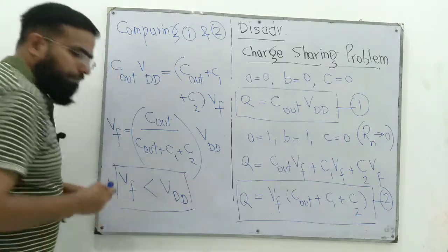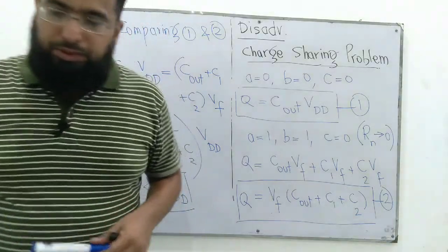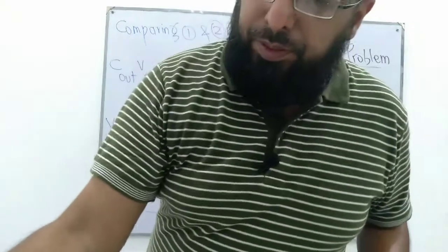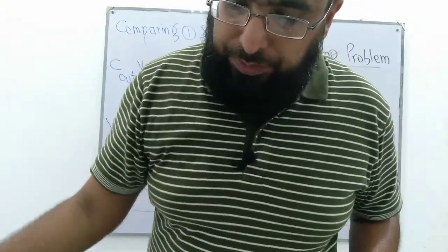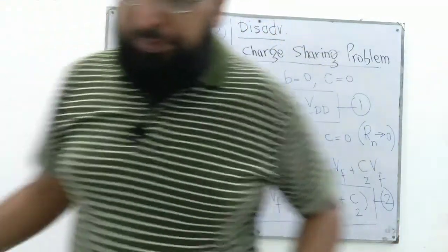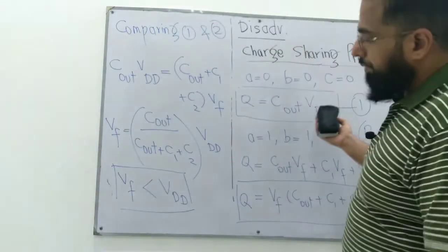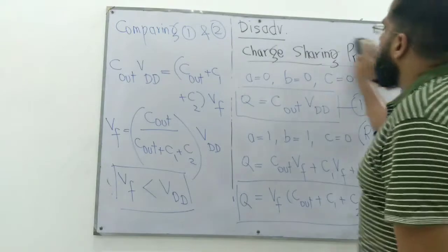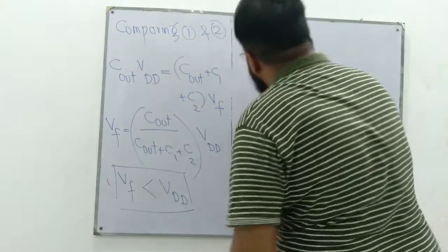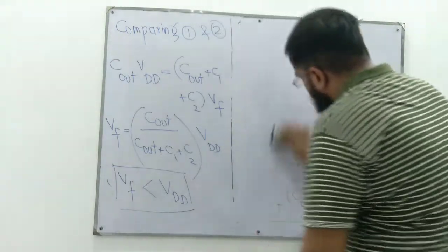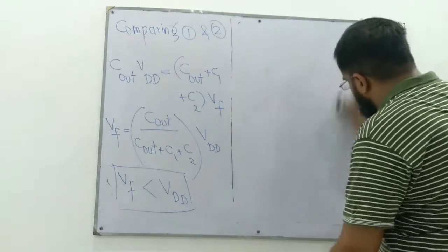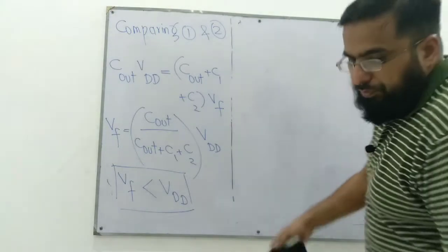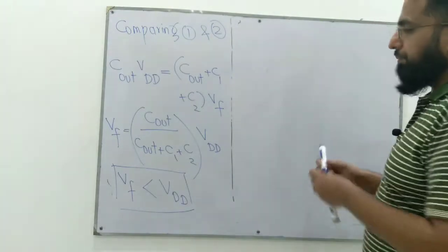It has to be, because there is some leakage current flowing through the capacitances of other paths. Which is not good, because the output should be equal to VDD when we are in pre-charge. The output is supposed to be VDD. So how to make it as close to VDD as possible?